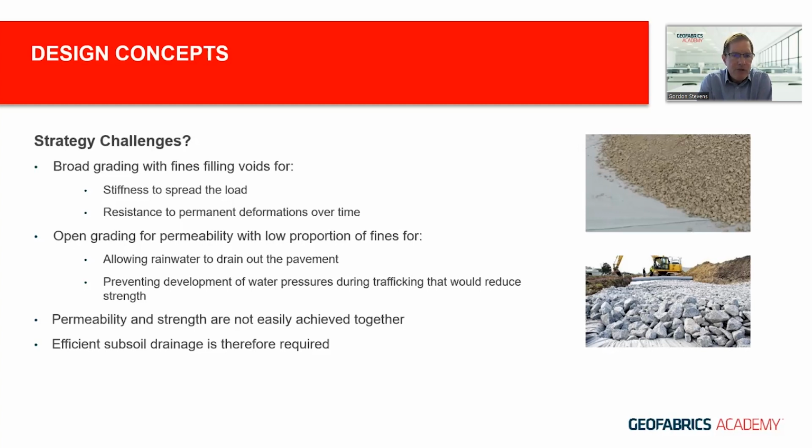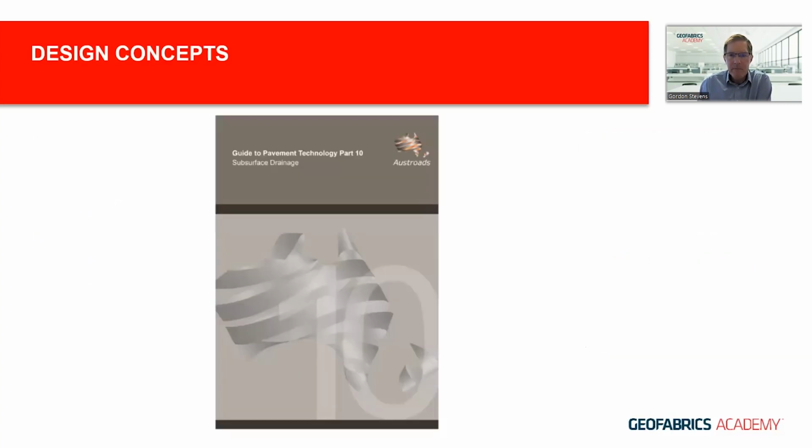So permeability and strength are not easily achieved together. And when it comes to drainage, efficient drainage is therefore required, as our main design focus is weighted more towards the broader graded aggregates for stiffness in our pavements. The Austroads Guide to Pavement Technology on Subsurface Drainage offers good guidance on this important area of design, and this is what we're going to be focusing on in the coming slides.